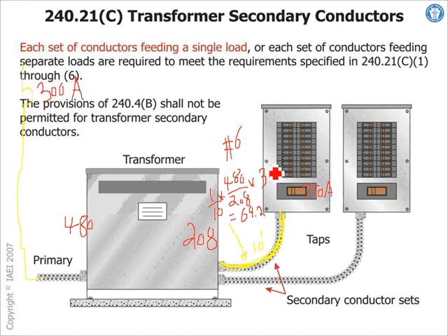I don't know, guys, how many of you know, there's also a rule that says the primary plus secondary conductor. So I'm going to use this one. From here plus from here, can you guys see that? The distance from this panel to this panel cannot be more than 25 feet.